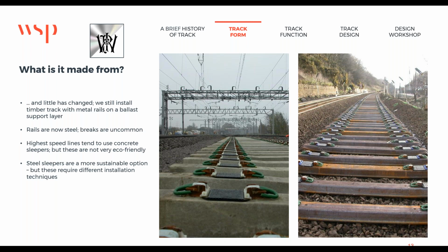Steel sleepers have elongated ends, which oppose the movement, and the concrete sleepers rely mainly on the frictional resistance between the underside of the sleeper and the ballast. Ballasted track forms are still the norm, as they were in the early days of railways. Why is that? Well, ballast as a track support can be fairly easily removed, it can be replaced, and it allows the track geometry to be rearranged to suit evolving traffic patterns and higher speeds.